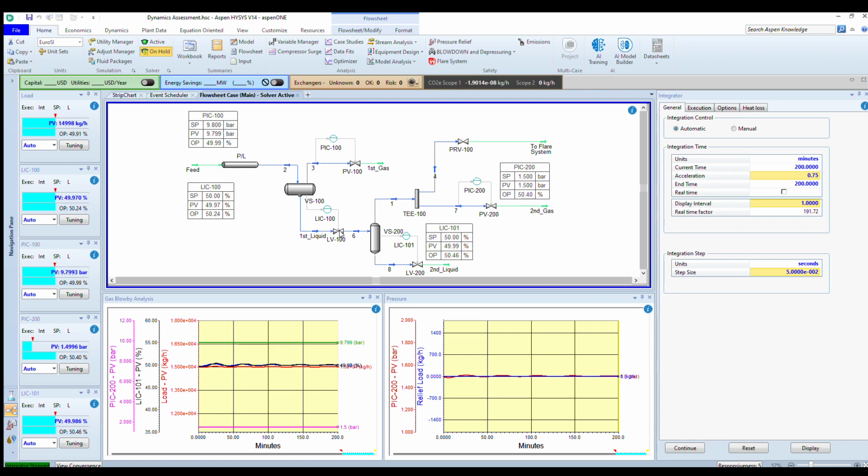And the definition of overpressure as per API 14C: if the transient pressure increases above the design pressure of the vessel, this is the definition of overpressure. So my key objective is to see the pressure rise in the LP interface, whether it is going to exceed the proposed set point of the PRV located on the LP interface or the design pressure of the LP interface. This indicates an overpressure.